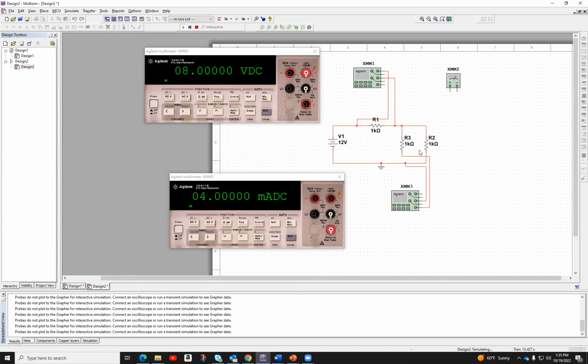As you can see, this is actually correct, right? Because if you do voltage division here, then you can see that you will get 8 volts across here, and so that's 4 volts across these two, right? In any case, that's how simply it is to make measurements.